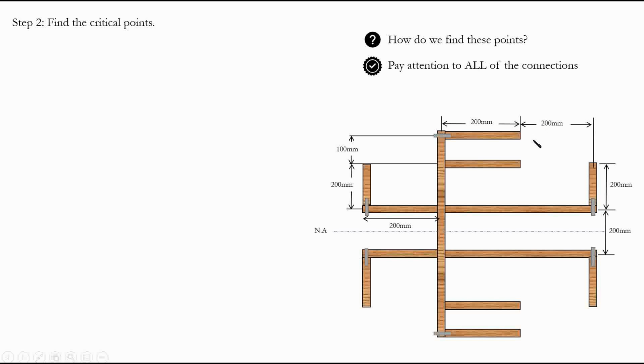And this goes back to the definition of shear, right? Shear is created when 2 planes are in contact. Now at the edge, there is no shear plane, right? So there's only one shear plane. So from one shear plane, you cannot get a shear stress in this direction, right? So in the direction that we're looking at. Now, the shear stress here is 0. And for this flange, the maximum shear stress is going to be at this point, right? At this point where there's a connection. Same here for this flange.